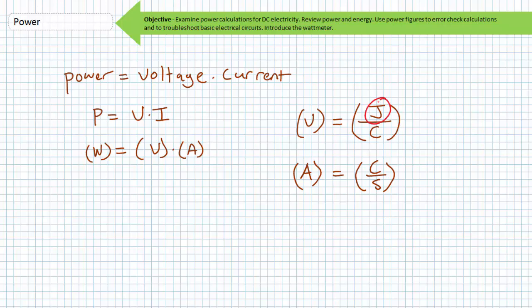That's voltage. Now make the group of electrons move into or out of a system. That's current. If the group moves fast, that's a lot of current, and a lot of energy is dumped into a system in a short amount of time. If the group moves slowly, energy is slowly input into the system. If the current is sustained, group after group of electrons arrives, each dumping its associated load of energy into the system. The time rate of energy arrival is power. The growing pile is energy.